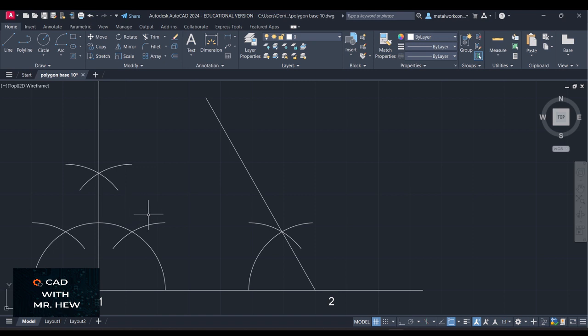The purpose of constructing the 90-degree angle is to bisect the angle to give us a 45-degree angle. Okay. All right, so let's do that now. So we're going to bisect the 90-degree angle to give us a 45-degree angle. What we're doing at 1, at the end of the line labeled 1, 2, we're constructing a 45-degree angle. Is that clear?